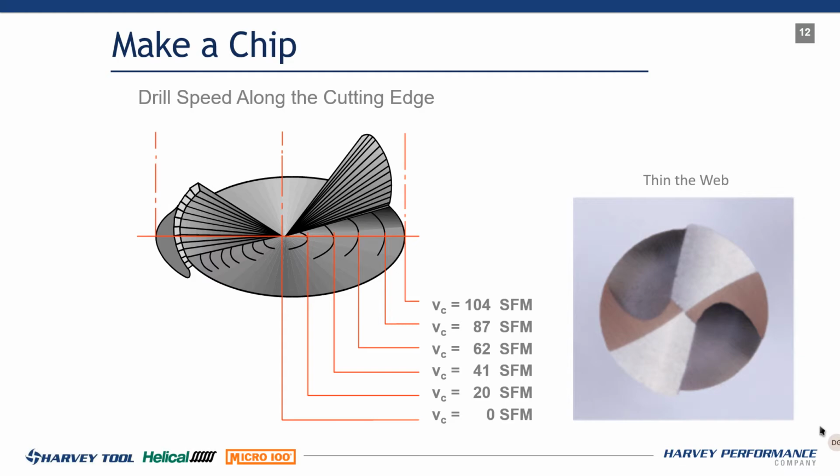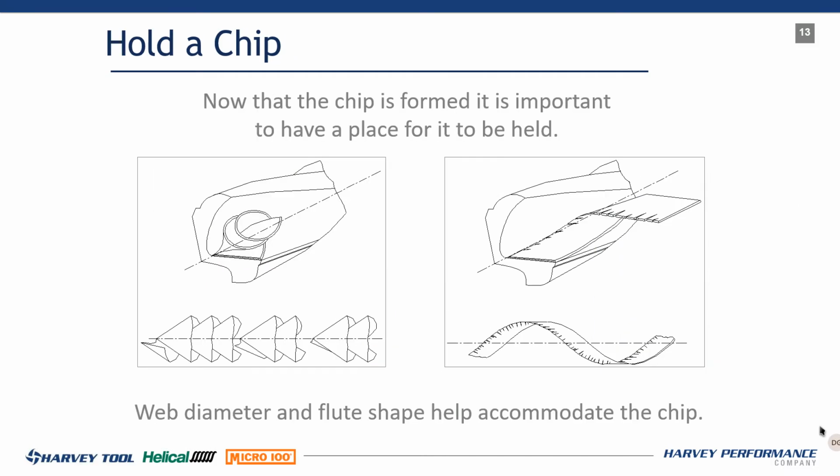We don't want that movement of the drill. You want to reduce the thrust force. You want to reduce the amount of force on the spindle, and you want that drill to just perform by using its cutting edge, by using its primary, its secondary, its web, make a round hole, hold the chip and evacuate it.